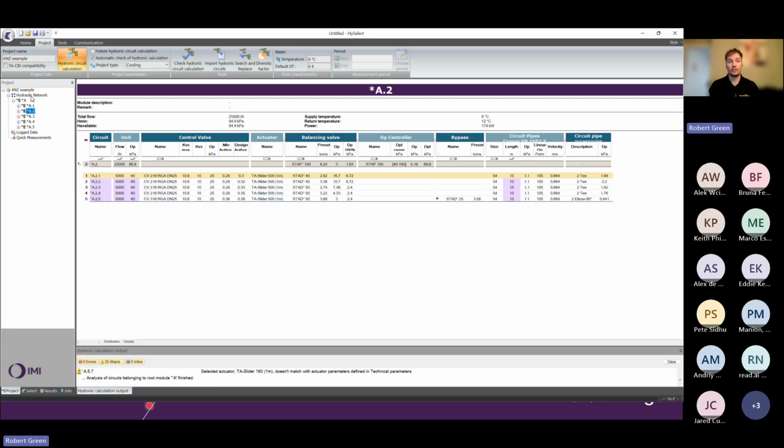It gets a lot more difficult if you're wanting to do diversity within a circuit. So say 5 control valves of 10 are open within a circuit. At that point you realistically need some form of differential pressure control somewhere else on the system to do that diversity, because you're sizing it to a lower flow rate. But it's certainly something you can look at, and in design it's very useful to get that from the initial design stage. In fact, I can show now, for example, how to add the diversity factor here.